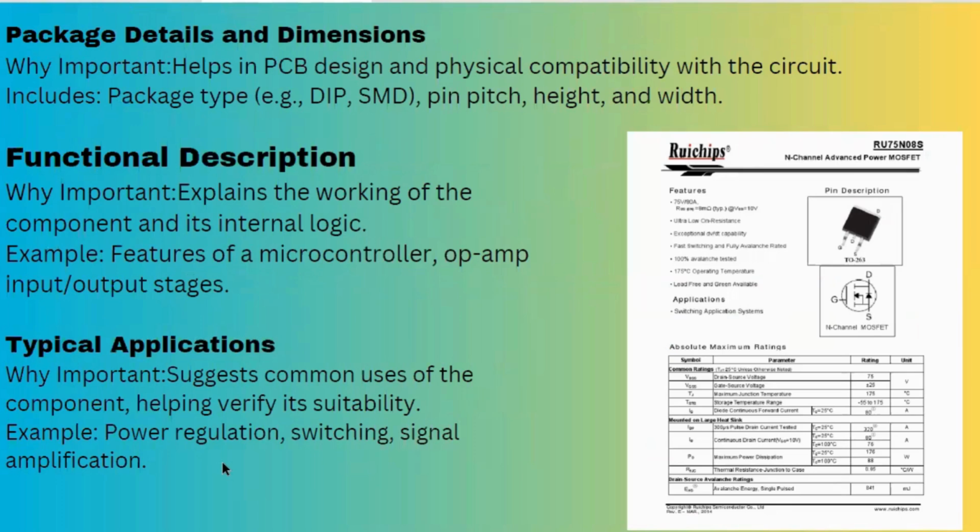DIP or SMD. SMD means surface mounted device. DIP is dual inline, which means pins are inserted inside the holes. Okay, so all this information will be coming from the package detail.